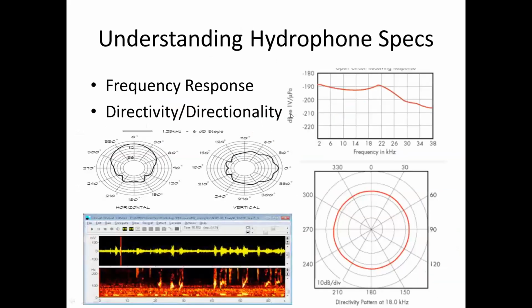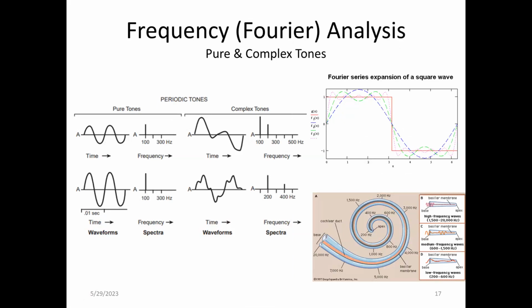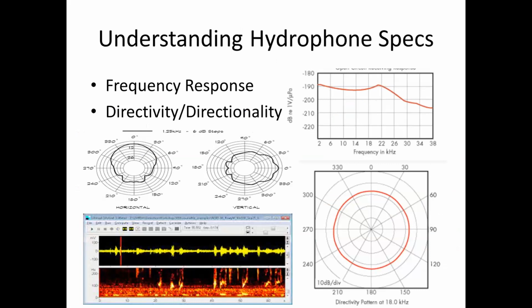Now that you have got the idea of the time domain signal as well as its frequency domain representation, I can tell you a little bit about hydrophone specification. A hydrophone, if you recall, is the same device as a microphone, and the projector is the same as the speaker in the real world on computers. Those microphones or hydrophones are represented by their frequency response and their directionality. The curve that you see on the right side is a frequency curve, and the y-axis is dB relative to 1 volt per micropascal. That means it's underwater sound we are looking at, because underwater we use this 1 micropascal reference.